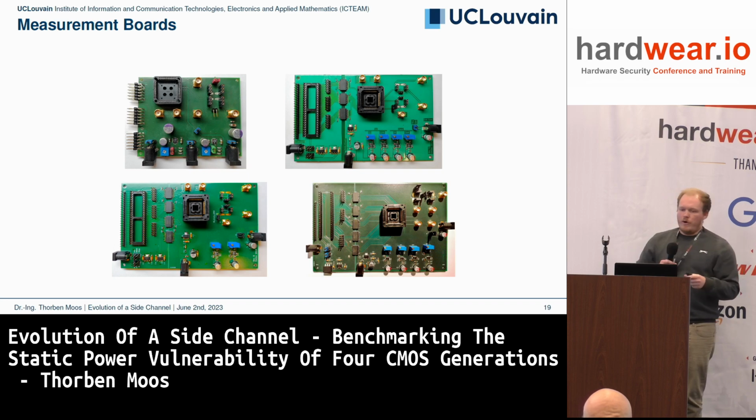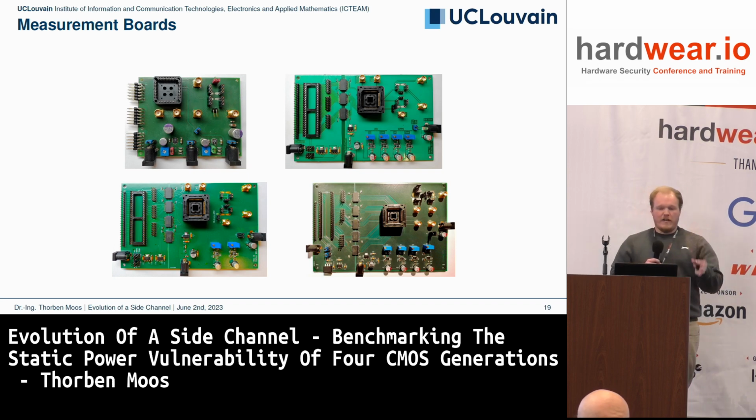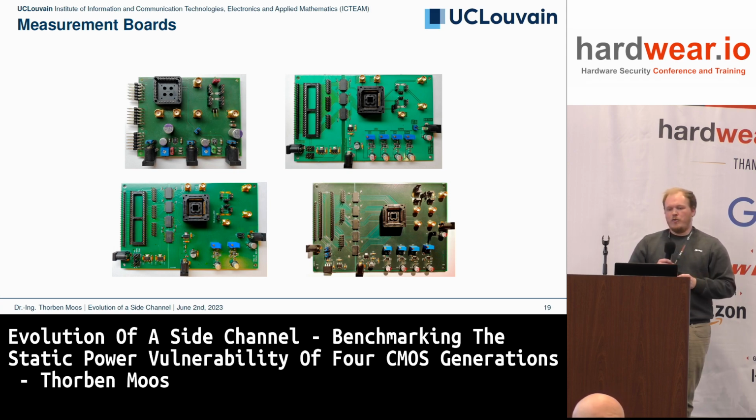What is very important is the separation between the left side, where you can plug this FPGA board, and the right side where the ASIC goes. So we have completely separate power supplies of both types, and we have isolation of the I/O signals in the middle, so they go through these expensive isolation devices to have a completely decoupled power profile on both sides.